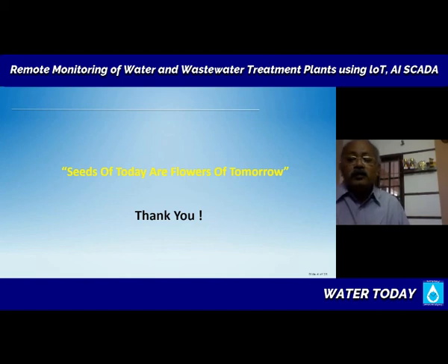It is very important beforehand, if you are going to initiate a project where you want a SCADA system with all these analytics, to know what is happening weekly, monthly, annually. I want to monitor these parameters. What are the inflows? What are the outflows? How much treated effluent am I generating? What is my water quality? A lot of data is there.